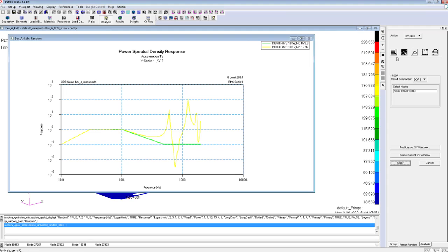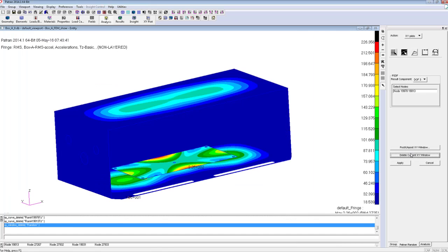If I were to look at the thinner box, we'll see a lot more response, and so it might actually push the wiggly lines, if you will, farther into the lower frequency range, and that would be very bad, and we'd have to really think about that. So generally this XY plot is what you look at to investigate your model.